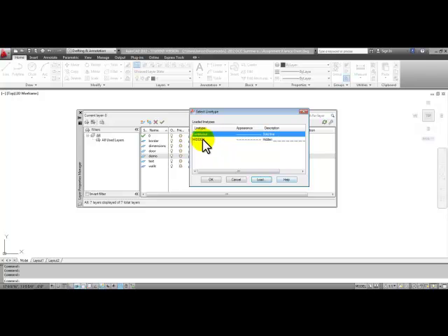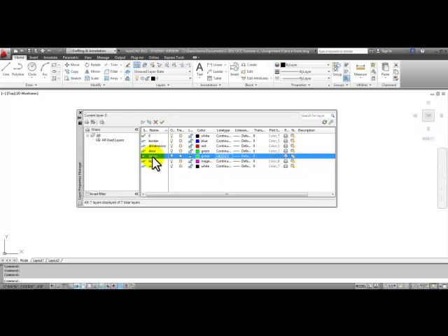We loaded it. Now let's highlight hidden here in this dialog box and pick OK, so that the layer called Demo is changed to the line type hidden. And because we're going to start by drawing the walls, we can double click on this little sheet of paper in front of walls, or just highlight your layer and pick the green check mark so that that layer is